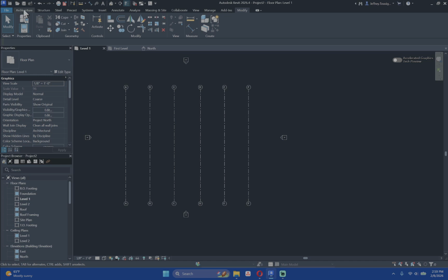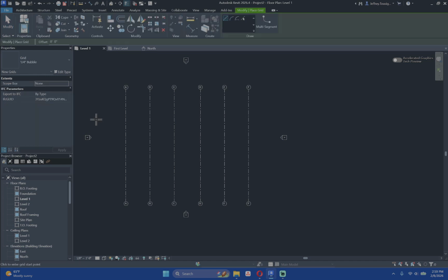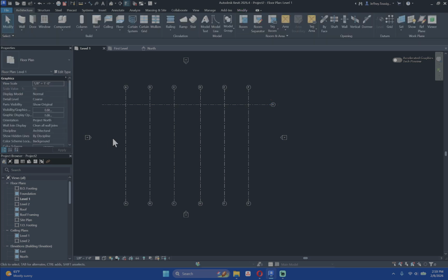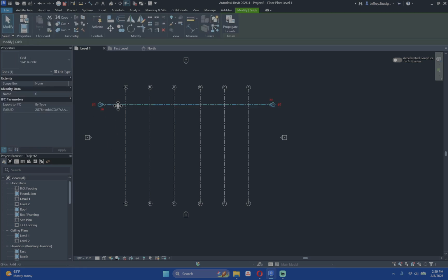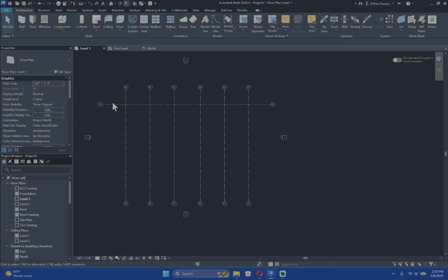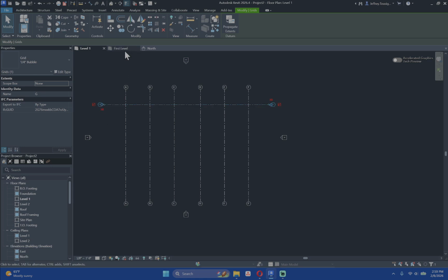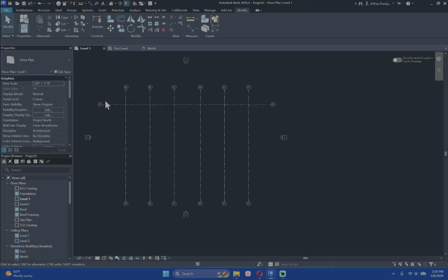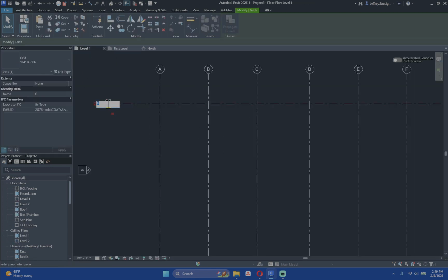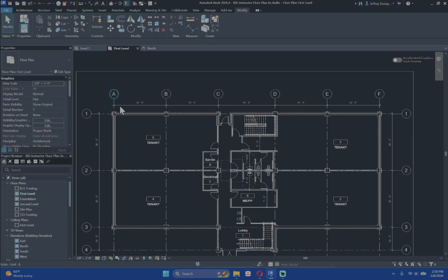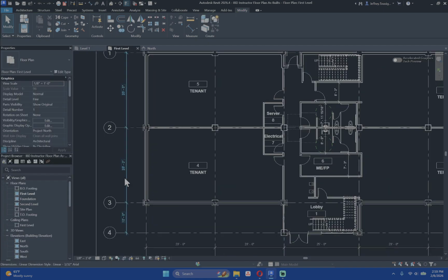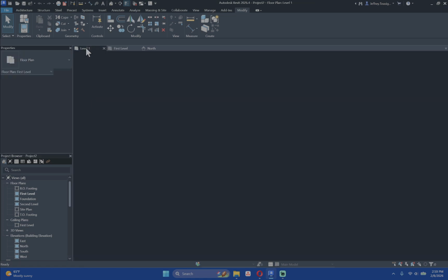And then we can do some horizontal ones now. So grid, draw horizontal. I think maybe if I turn this on and then copy it, maybe it'll be on both sides. But this one needs to be 1 at the top. And then copy it down. And these are 25, 25, and 10 feet apart from each other.